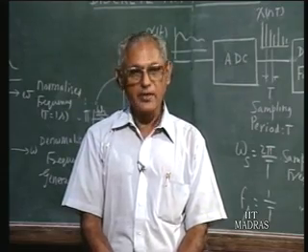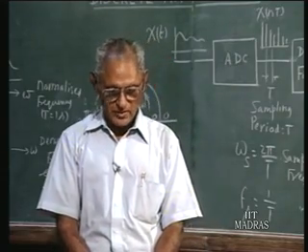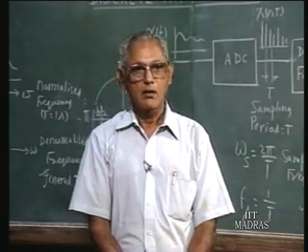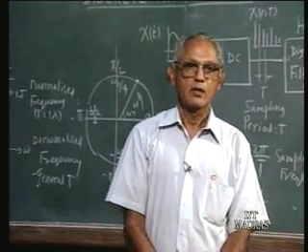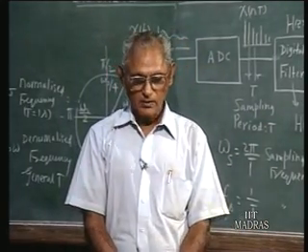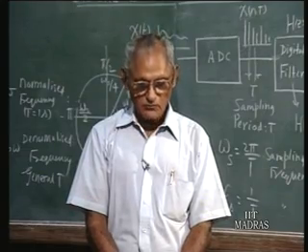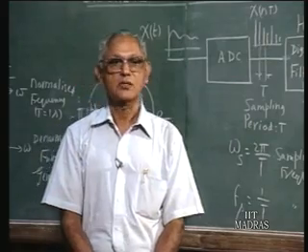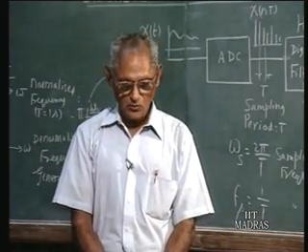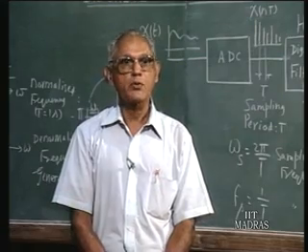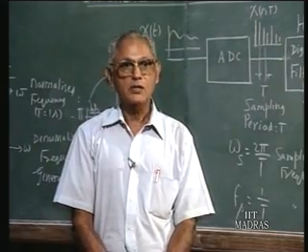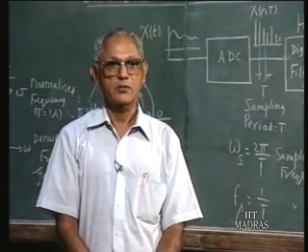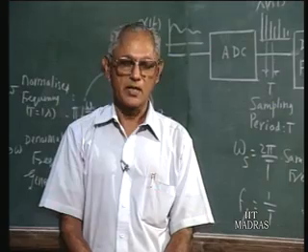We looked briefly at the classical method of solution of difference equations, and then afterwards we studied the operational methods, the transform methods, applicable to a discrete time system. This particular transform is called the Z transform, which is the counterpart of the Laplace transform in the continuous time case. We saw the various properties of Z transforms, and we saw how the Z transform enables us to convert a difference equation into a purely algebraic equation, and then we worked out a few examples showing the efficacy of the Z transform method in the solution of the transients associated with the discrete time system.